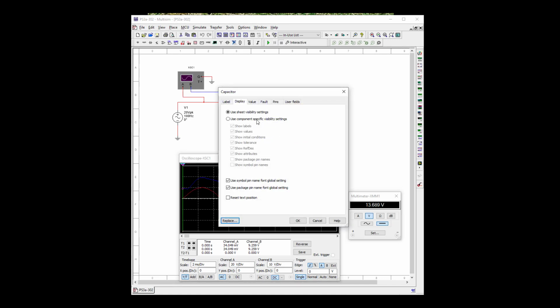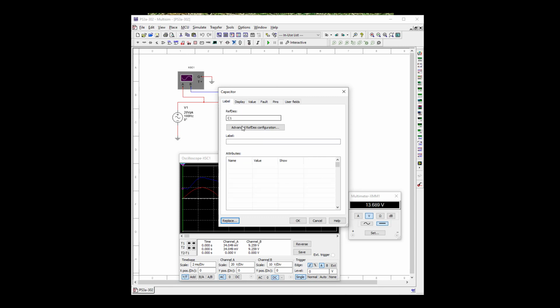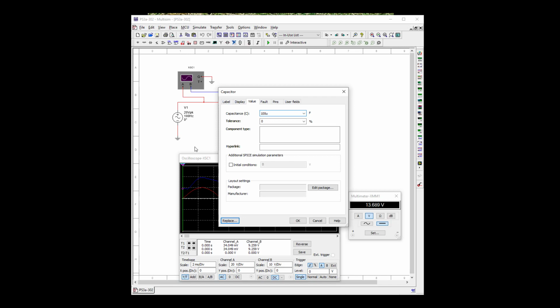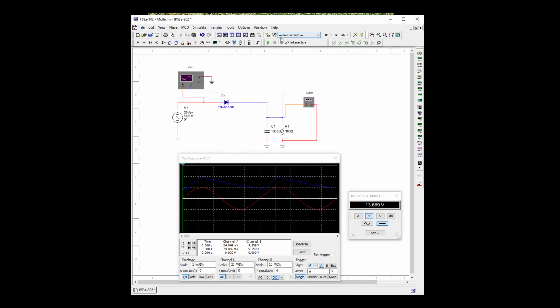So let's go ahead and go to 1,000 here. And you see how smooth that is, and we got more voltage out of it. So the larger the capacitor filter, the smaller our ripple, and the better the DC and the higher the voltage out. So okay, let's go ahead and shut this down and open up our last file.